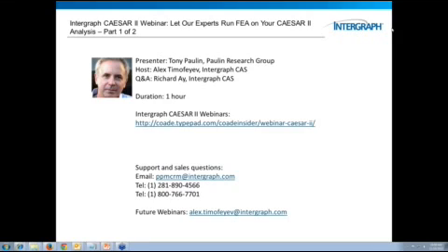Yep. So now they've gone from a flexible system to a lot of intersections, and then using ASME code, they don't get any flexibility in their system. So I thought that would be the perfect candidate for FEA tools because it's hot, it has cycles, and a lot of flexibility is lost by removing the elbows. That is just like the example S303. That would be a perfect illustration of how to run the software, or why to use it.